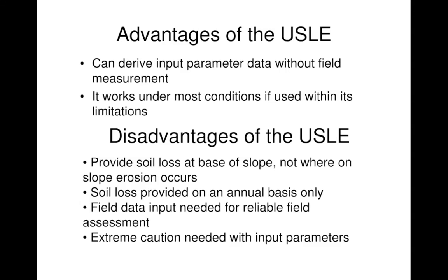The advantages of USLE, if there are any, I'm very skeptical about that. You can derive input parameters without field measurement. Well, that's a load of bull, if you ask me. And it works under most conditions if used within its limitations. Well, yes, it works if you've done all the experimental work at your site. So there's no getting around USLE unless you've done your own measurements.